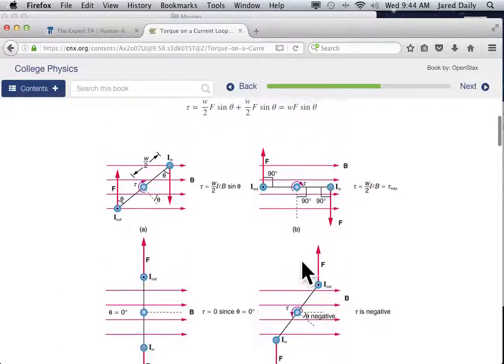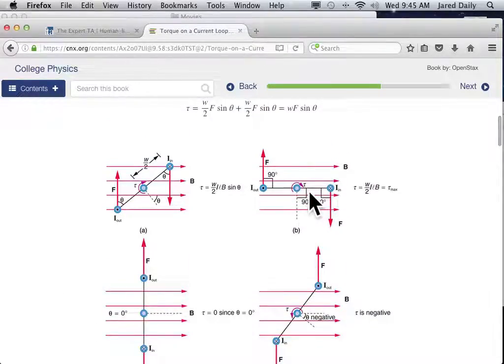The problem is that when you're directly in line with the magnetic field, those forces are very strong. But if you're lined up, so in this particular case, this is one side of the loop, this is looking from the top, the other side of the loop, and this is the axis of the loop. When you're in this situation, you get these forces that actually point outward like this, and the loop will just get stuck here.